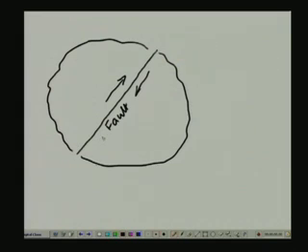So in this case, the principal stress in the vertical direction is going to be 0, because the rupture is taking place at surface, and the two principal stresses in this case are going to be aligned in this direction, and we are going to look at the configuration in greater detail later on in this lesson. So this problem is essentially a plane stress problem.